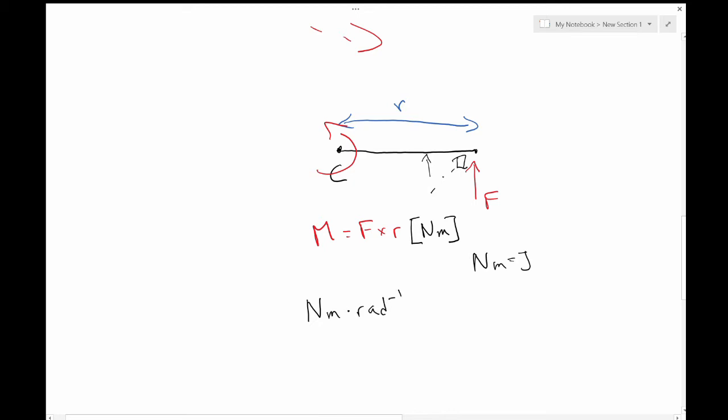So that means that in the same way that force times distance results in a certain amount of energy that it takes to push something, a moment times the amount that you rotate it, the rotational force times the amount that you have to rotate, is going to give you energy once you multiply out this radian term. But because radians are technically dimensionless, that doesn't make it into our actual units for the moment.